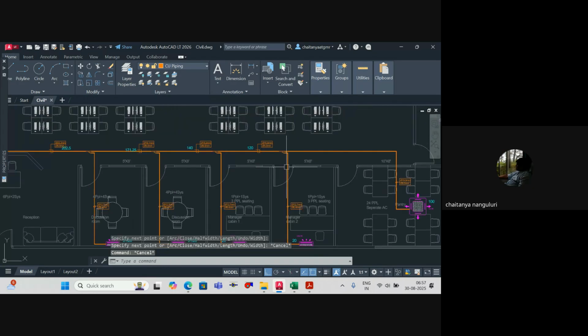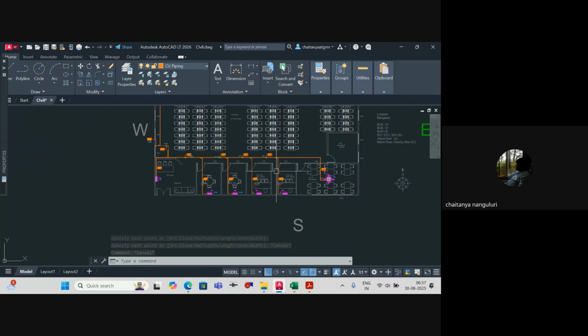Without that, you will not be able to. So you will basically select all the indoor units. You have to find out the capacity index, keep adding on the capacity index. Then you have to choose the branch size, main header pipe size, and outdoor to first ref net size. Understood or not?